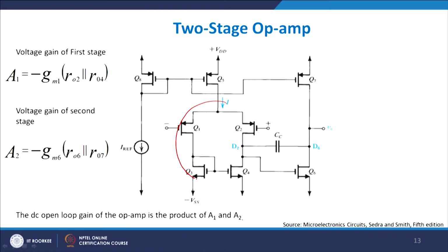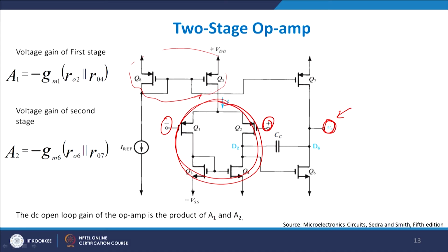But if you look very carefully, this is nothing but a replication of the BJT differential pair. This is the differential pair which you get here, and this is the differential pair which you get here, where I am giving the input differential signal here, and this is the single ended output which I am taking from this arm. So this pair is responsible for impedance matching, this one is responsible for giving you a large gain, and this one is responsible for again impedance matching and giving you a proper output. So there are 3 stages available here.